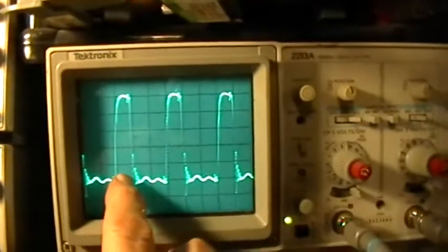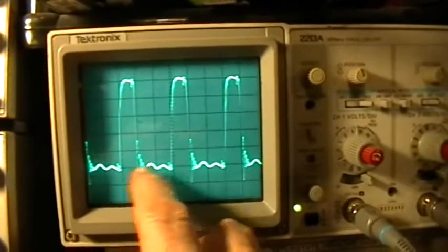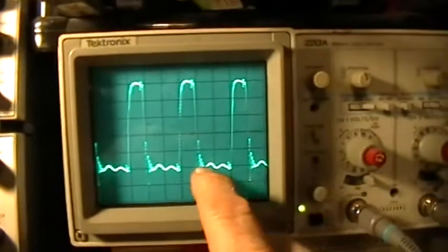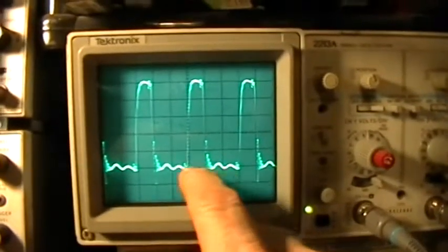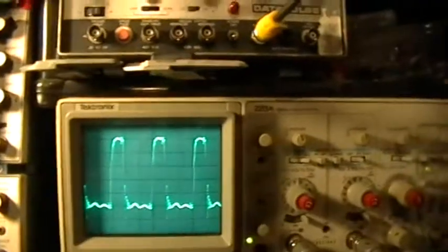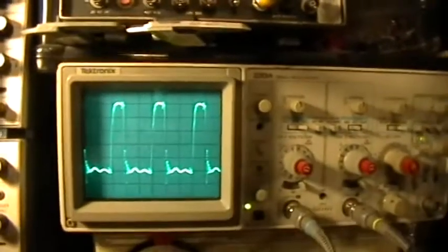And as you can see, I've got the display set so that, and the duty cycle set so that the on time is 1/3 of the period. Right, so we got 1, 2, 3 full divisions for the period there. And this is happening at a frequency of 164 kilohertz, 164.4, driven by the function generator this time, to give a nice square-ish kind of pulse.